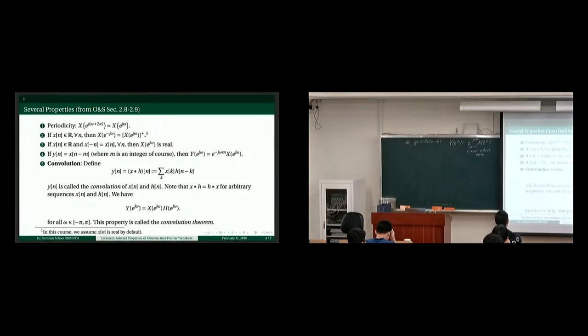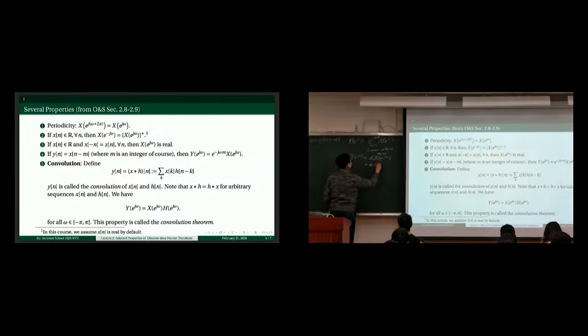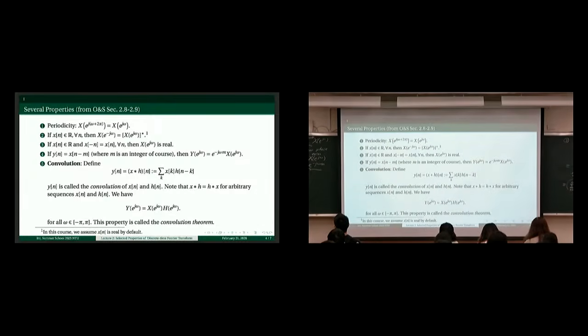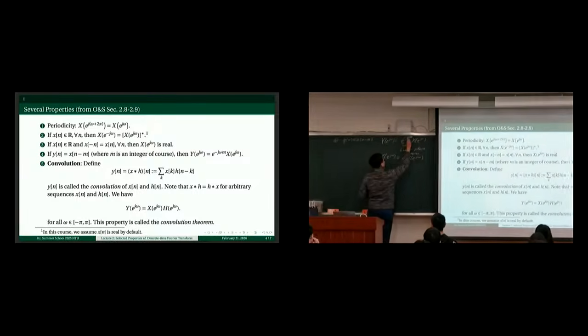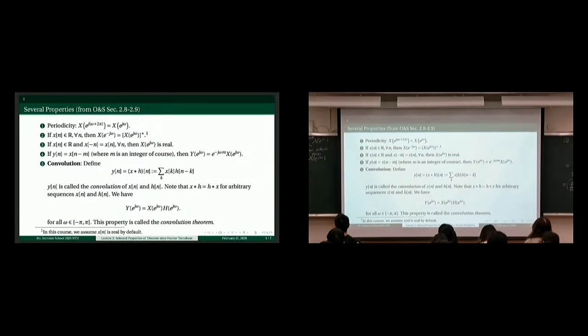So that is to say, if you take the phase spectrum, it equals the phase spectrum of X plus the phase of e to the minus jωm, which by default is the extra term right here in the exponent. So we simply say minus mω.